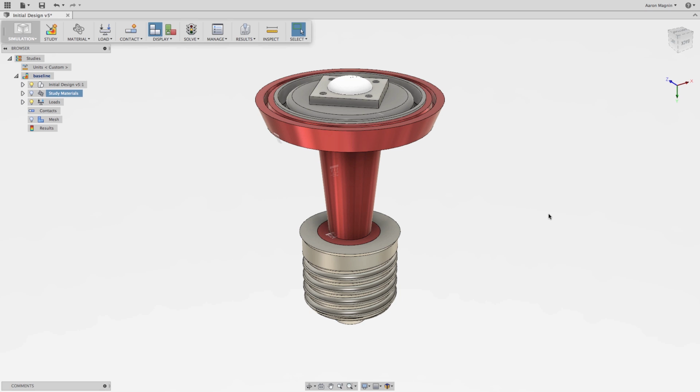And it looks like we're well along our way to setting this problem up. I mean, it really is that easy. Now, if I were to run it right now, again, it's not going to carry the heat away from the diode. And the reason for that is that you need to deal with how bodies can conduct or insulate from one another. And the way that you deal with that in a thermal simulation is using your contacts.